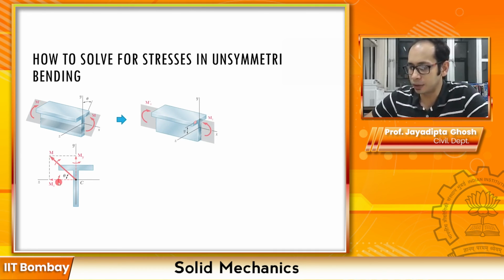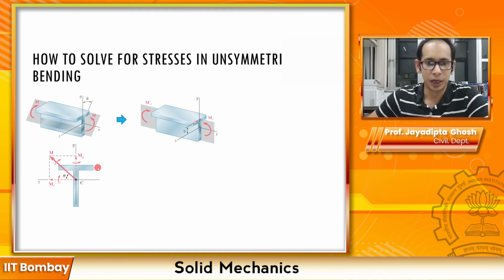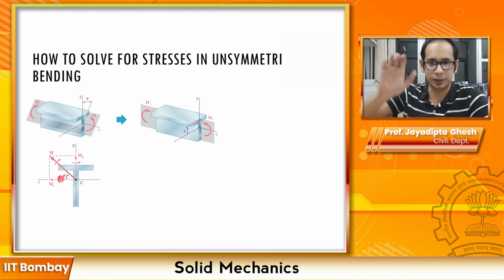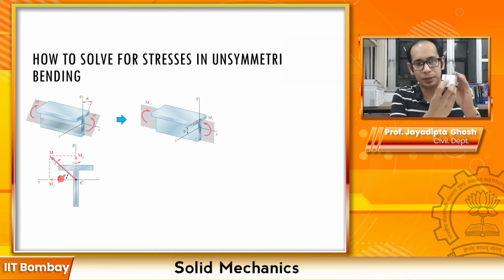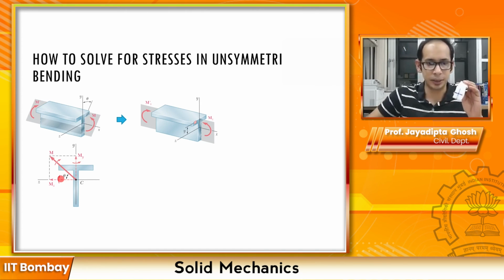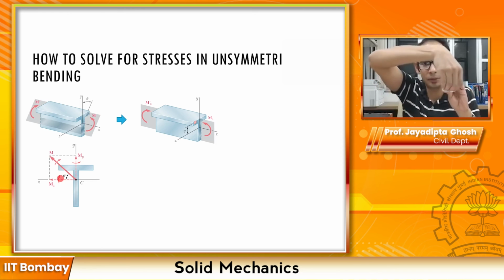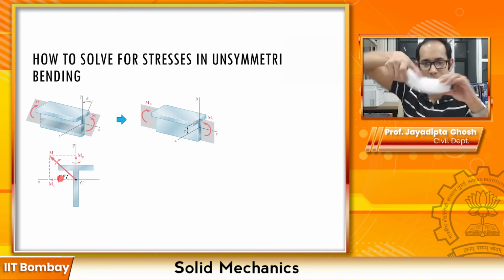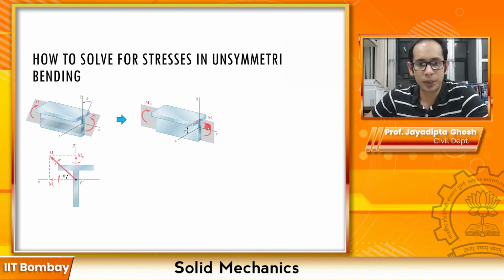So for the first one, this is the Mz over here, which is acting like this. And why is it acting like this, you may ask. Mz is pointing towards that. Now follow the arrow and the curved line over here. It is pointing like this, right? So that means that if this is my zz axis, this guy on the screen is marked like this with the finger curling. So that means my beam is bending like this over here, right? The beam is bending like this. My finger is curling like here, right? So this is how the moment is acting, Mz.